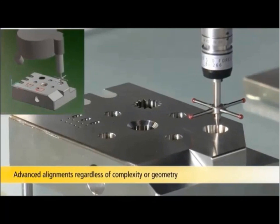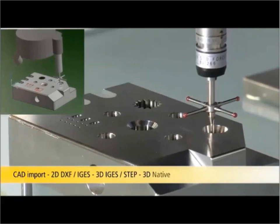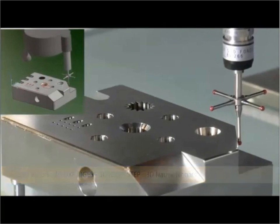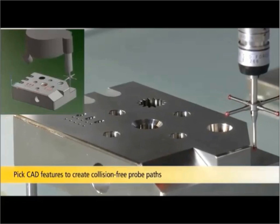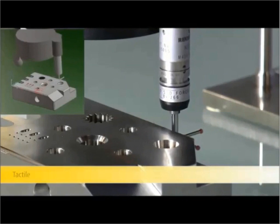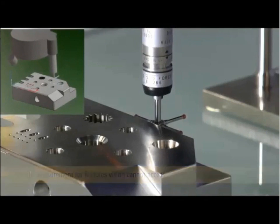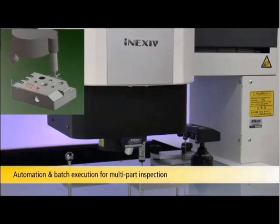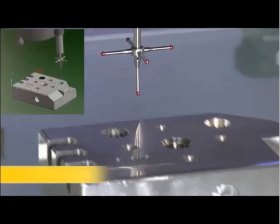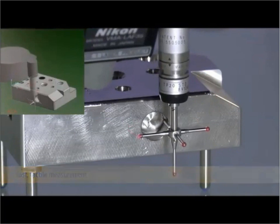So we can seamlessly, with this path planning engine and CMM Manager, transition from a vision measurement to a laser autofocus measurement to a tactile probe measurement. And of course, when we're picking features on the side of the part, automatically the software can create a path that moves the probe from one location to another and safely access all of these different types of features that we might be interested in. So immediately after measuring this feature on the back, we'll move to the front of the part, and you'll see, again, a path that was created automatically where we move to the circle or this hole on the front side of the part.